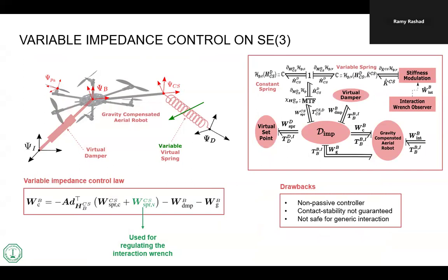I have this desired frame in this figure, I say go there. And usually you have an environment in between. And you're pushing, so you already have contact. You already have a contact force. It's not just the one that you want. So what do you do? Just increase the stiffness. That's it. And then until the force that you're already pushing with becomes the one that you want.